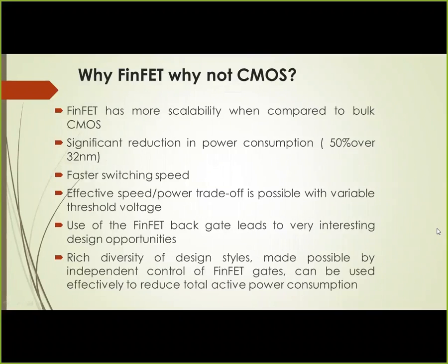First of all, we have to know why we are using FinFET instead of regular CMOS. FinFET is nothing but the adoption of CMOS at the nanoscale. When we go into the nanoscale, that is below 32 nanometer, we have scaling issues for CMOS, and that's why we are going for FinFET. And FinFET switching has some advantages over CMOS, like switching speed, etc.